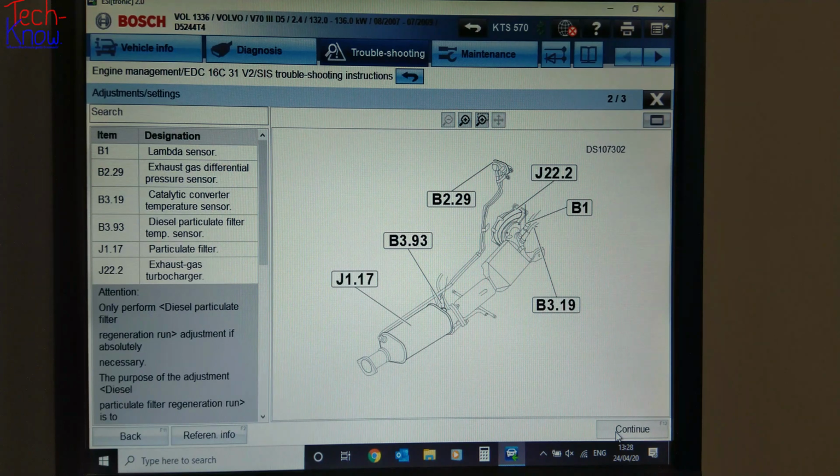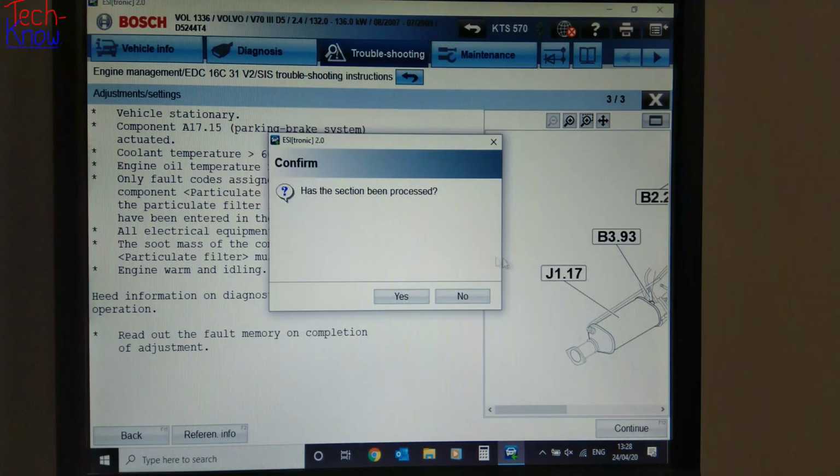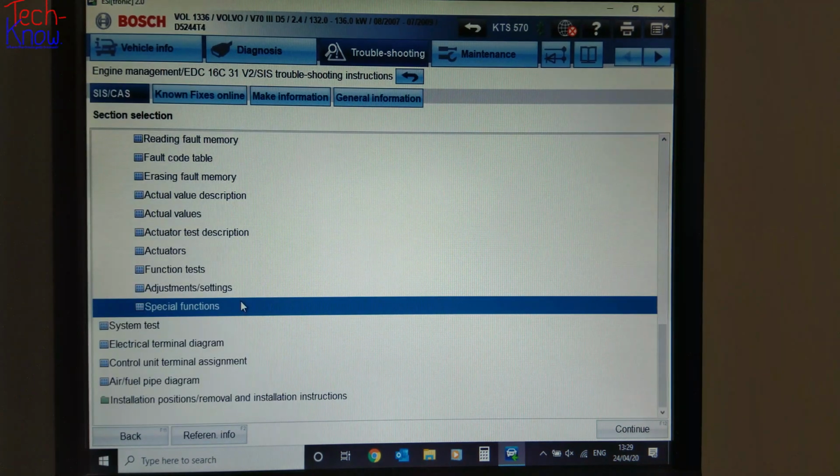Let's say, for instance, the camshaft position sensor. If I click here, it opens up a section all about the camshaft position sensor and the possible faults that could be detected by the sensor. If I click on here, it will show me the functional operation, how the camshaft position sensor and crankshaft sensor actually work. Once again, we've got sample waves here. Click on the expand button.